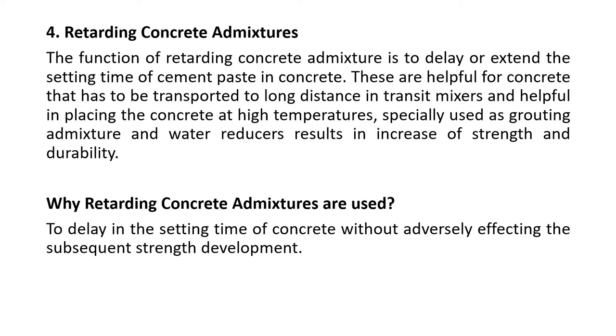Especially when used as a grinding admixture and water reducer, they result in an increase of strength and durability. Why are retarding concrete admixtures used? To delay the setting time of concrete without adversely affecting the subsequent strength development.